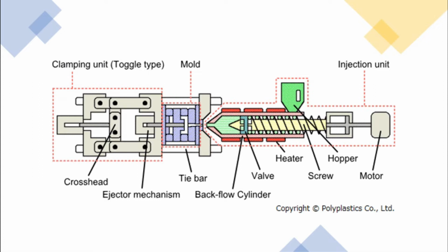The functions of the injection unit are to melt the plastic by heat and then to inject the molten plastic into a mold. It consists of a barrel or a cylindrical pipe. A hopper is located at one end of the barrel. A hydraulic ram or a rotating screw driven by an electric motor, used for providing force, is located inside the barrel.